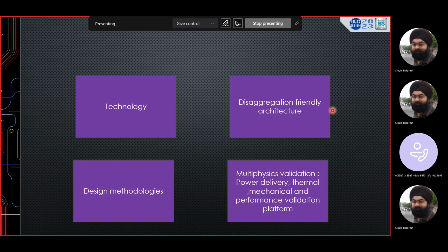I have an RTL which is a single structure today. How can I really create seamless partitions? Some part can be designed here, some part can go here. And if there is functional orthogonality, can we really push something to a lower technology node? How can I design the clock where the frequency of operation is what it must be, not overclocking, because overclocking also costs extra.